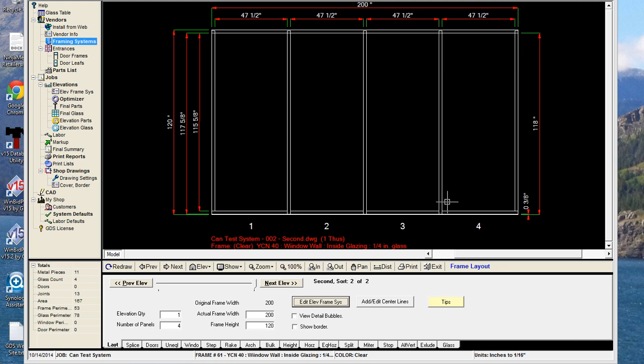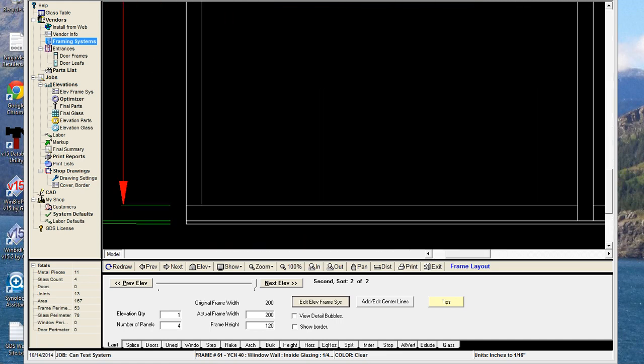Oh, okay. I was thinking it was going to give us too much on the verticals, but we're good. As long as this is the actual cut length you want, as long as it butts up right here, then we're good. I guess it has to if it's a regular filler material. It's not a pocket anyway, or it's not a receptor. So basically you're adding 1.5 inches to the length between the top of this sill component, actually a combination of the top of this sill component and the subsill.